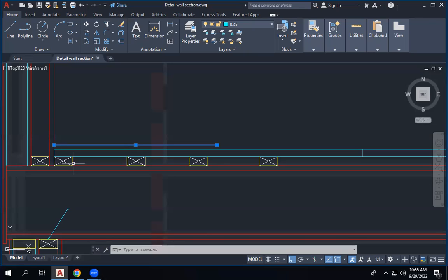So, bottom offset. You take it as one and a half inch on the tip panel, the tip base. Okay. 1.5, one and a half, yeah. And then the top one, it depends. If you use laminated floor, it will be 1 inch, or otherwise it will be tiling, it will be half an inch or 1 inch. So this one depends on the features. If it's a carpet, it's less. But the other one is 1.5. You need to have 1.5 because your load is putting into that base.